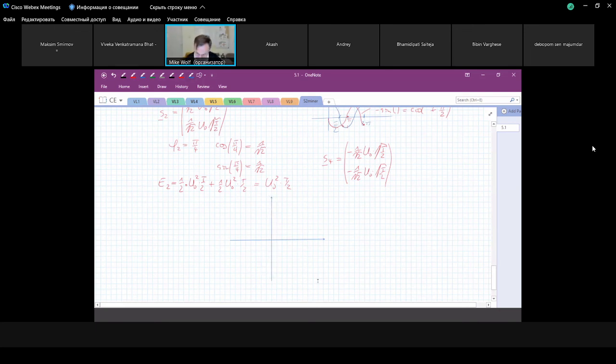We have 8 signals. We can transmit 3 bits with 8 signals, basically. And we can encode the information by a change of the phase of a cosine carrier or sine carrier. So let's say this is our spacing. This is again our spacing. And we define again, just for this drawing, A is equal to u naught times square root of T by 2.